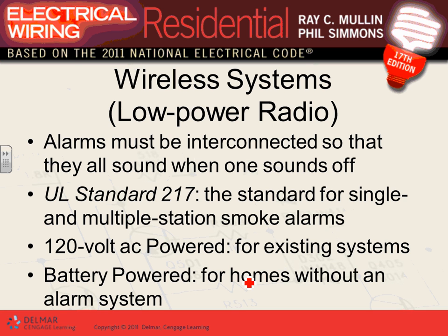They're interconnected through wireless. They're UL standards, so they're listed. They might not be approved by every authority. We still don't trust wireless when it comes to life safety, so a lot of these have to be wired. Smoke detectors in a commercial industrial building must be wired.